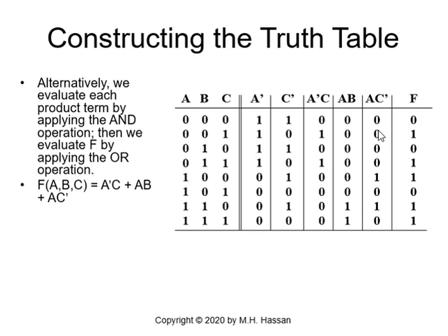The same thing we do AC prime. We will AND this column A with C prime. So 0 and 1 is 0. Okay, then we'll generate all zeros. Then this one will be generated with A, which is 1, and C prime, which is 1, and we'll generate 1. This is the only one generated.